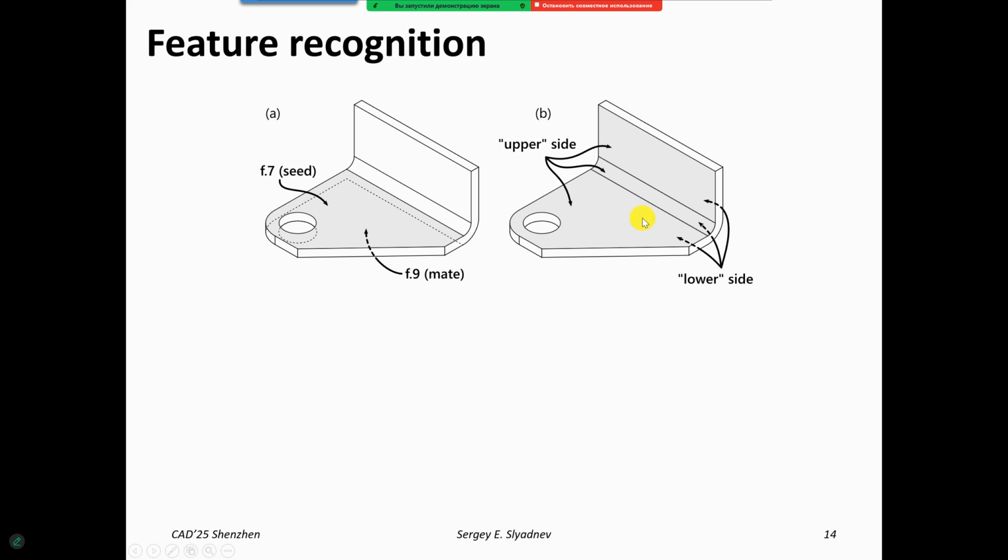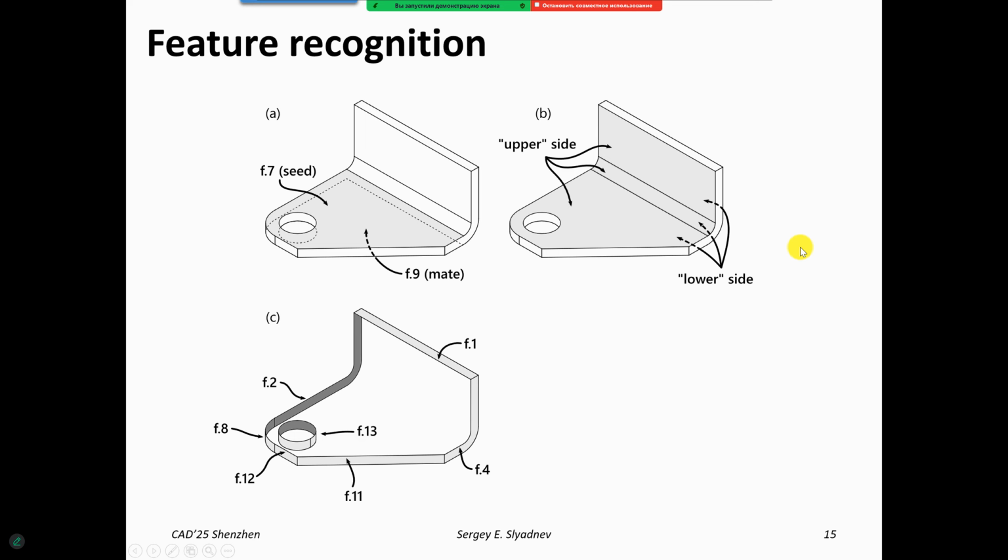This way we accumulate those shells, and here we can already check that we have exactly two connected components in the graph. All the faces that remained uniterated we declare as thickness faces, and for them we check their own subgraph. Basically here we check that if we have a loop, then it should be closed, and the degree of each node is necessarily 2. Sometimes we have just one isolated hole, which is a degenerate case where we have just one floating node of the graph. This is also okay.